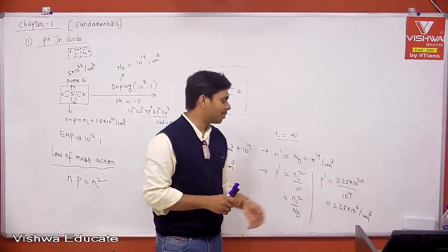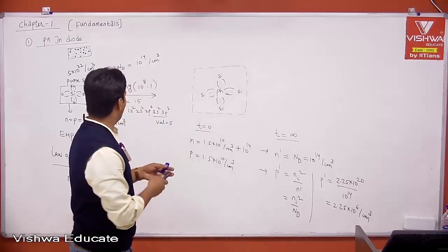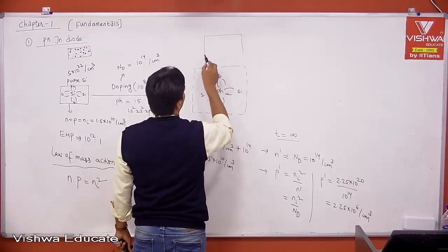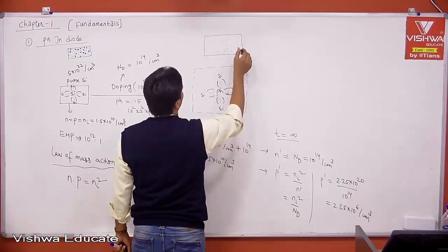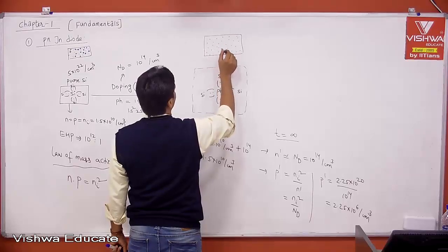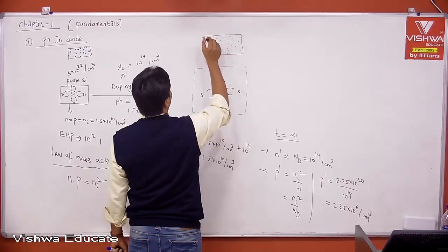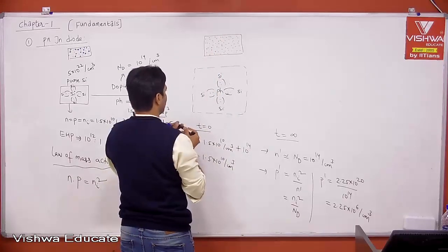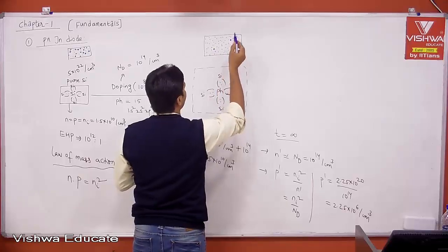That is why people say the hole concentration in N-type semiconductor is very less. Therefore, people call them minority carrier concentration. Therefore, now your majority carriers are electrons. The same thing can be carried forward for the holes also, and you have minority carrier concentration of holes.